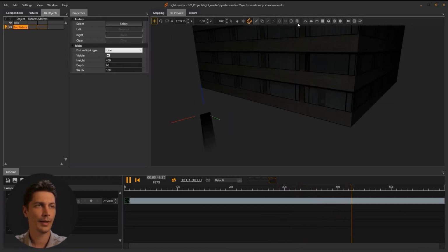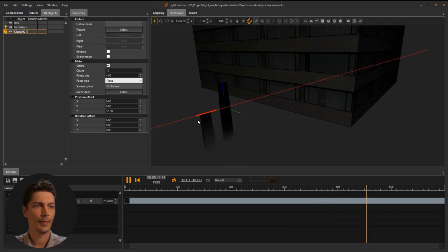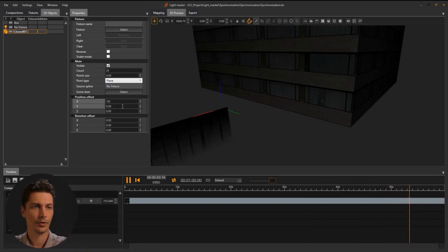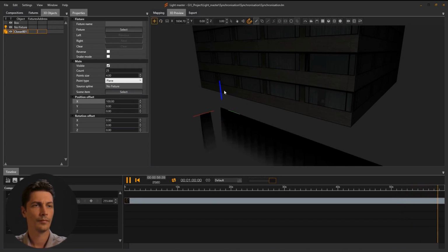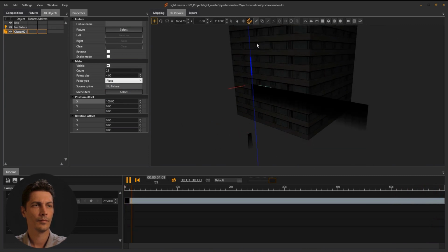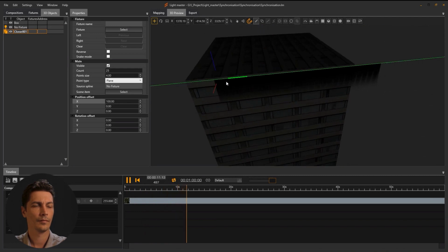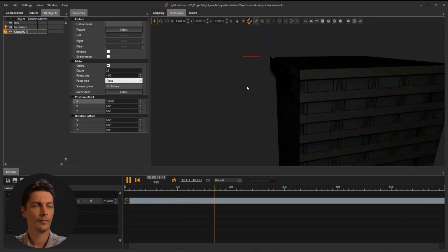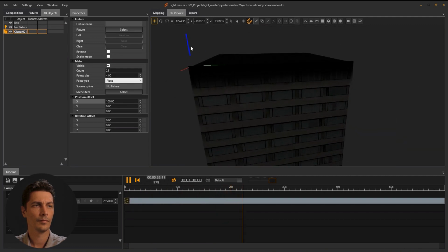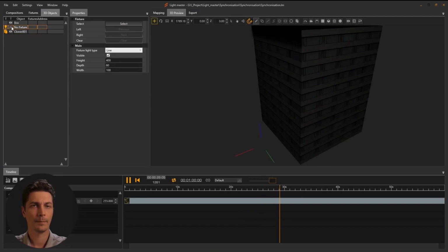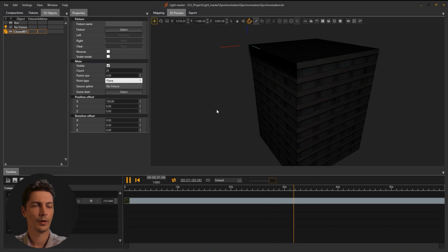We select our device and select the cloner tool. At this stage, we have the option to specify the number of devices, which, in our particular case, is 25, as well as define the offset on the axes. We will unfold and place it on our facade. The device from which the copies were made can be concealed. Duplicate the row of spotlights to the neighboring facade.